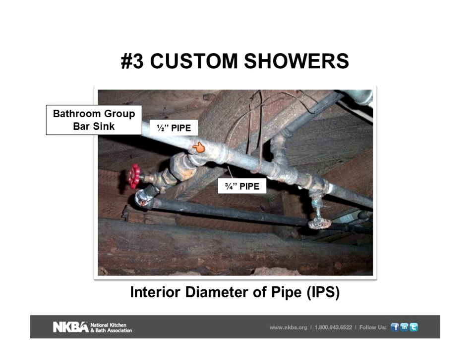At the time that I took possession of this house, we had a 1/2 inch water line going to 4 fixtures in that home. Now, eventually, we were going to add a clothes washer beyond this point, so we'd have 5 fixtures on a 1/2 inch water line. So what we had to do, obviously, is go back to the source of the 1/2 inch water line and upgrade it to 3/4 of an inch. And of course, then with the 3 or more fixtures, we were fine with that.